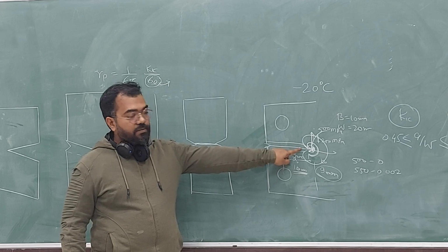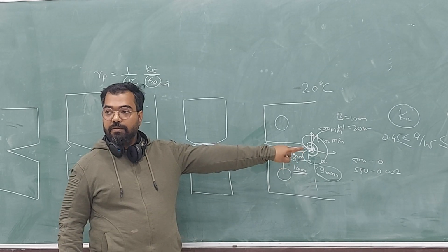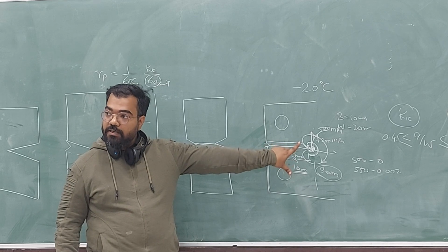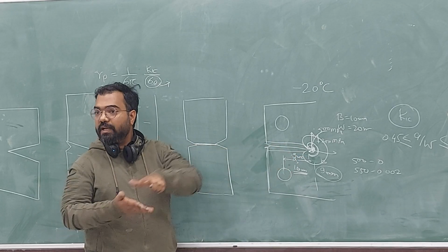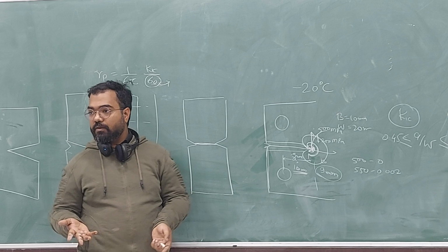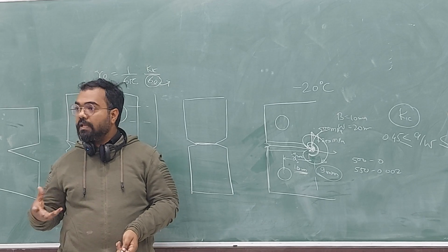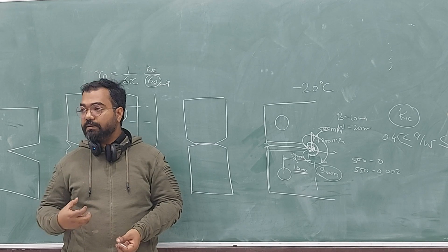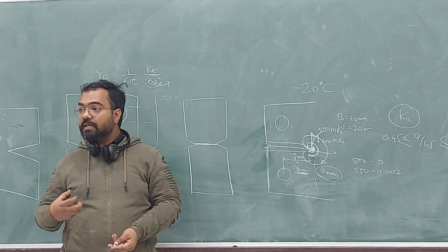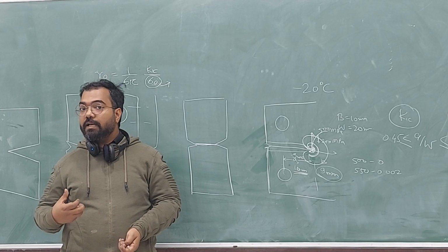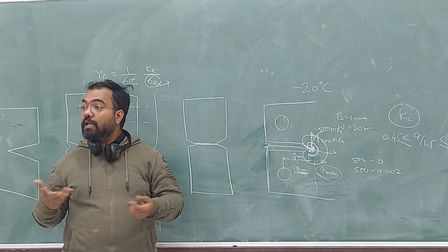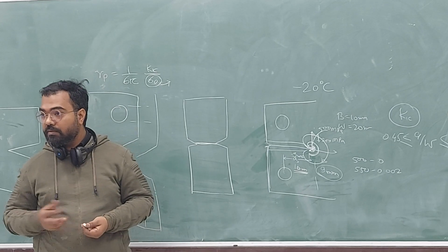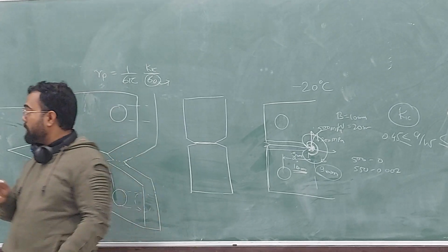We create this pre-crack so that it becomes sharp. And fatigue pre-cracking is also done in mode 1. Fatigue pre-cracking is monotonic crack extension under cyclic loading. And we know that when you apply cyclic loading, things will damage easily. Right? In high cycle fatigue, what happens? A material can break even at forces which are elastic. Right? Or wrong?